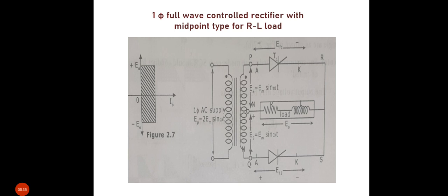then N. When omega t equal to pi, supply voltage is 0 and load voltage is 0. But the load current is not 0 because of the presence of load inductance. The load current decays at a point beta, which is shown as extinction angle.